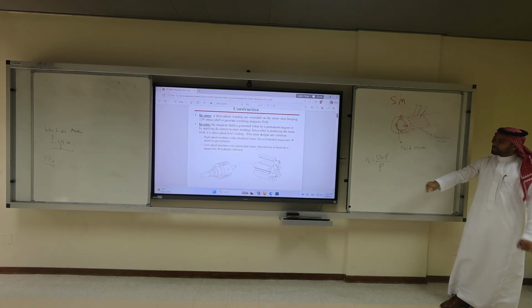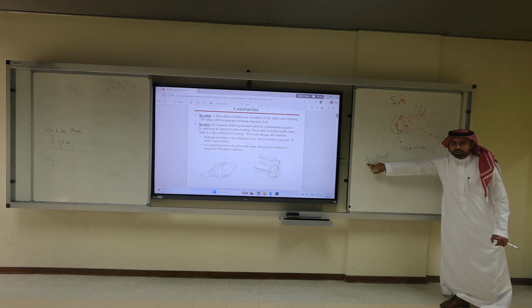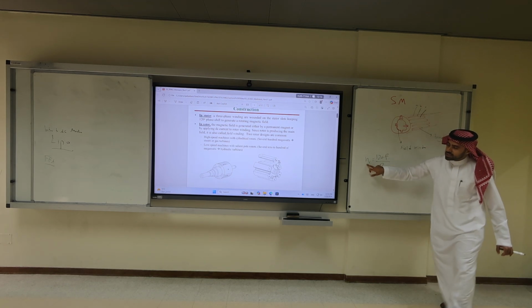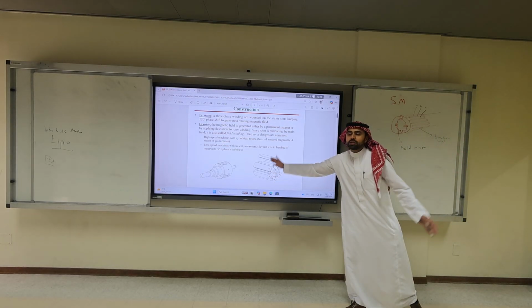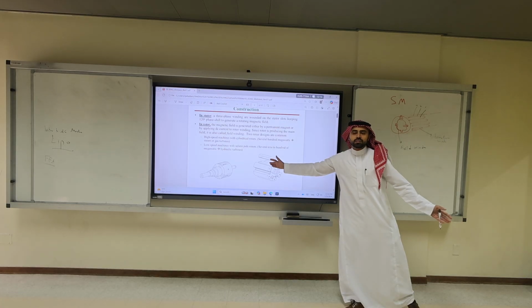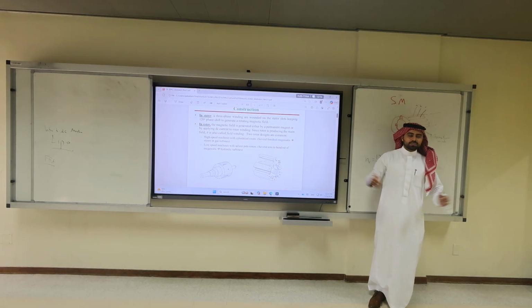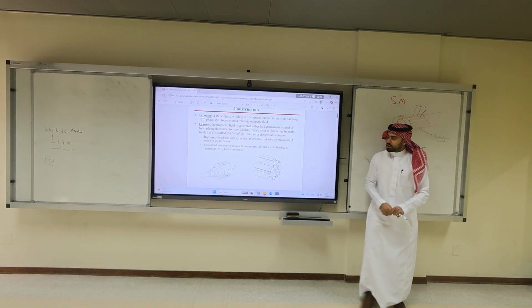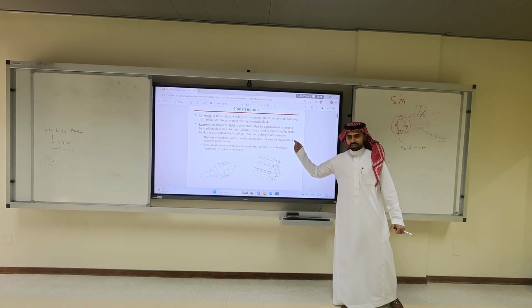Both are the same. So if you increase the number of poles, the corresponding synchronous speed is less. Because the corresponding synchronous speed is less, the salient pole option is a better selection, because I don't care. It's low speed. It doesn't matter if they revolve around the air at low speeds. The bigger the machine, the slower it becomes, the higher the number of poles, the more you're going to see it salient.